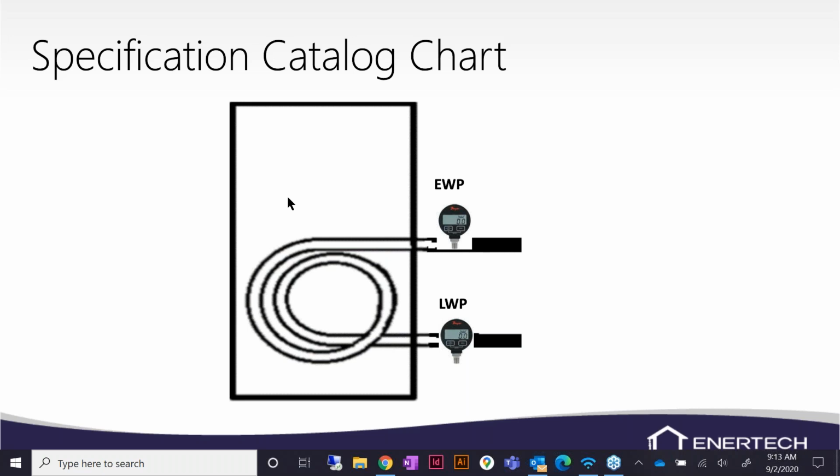We'll get to that kilowatt reading here in just a second there, Jason. When we get over to that I'll kind of explain that a little bit as well. And that kilowatts is basically just the compressor though. It's basically checking the power supplied in order to get the BTUs out of the unit. So we are just looking at the compressor on that. Okay. So again, pressure in, pressure out, and do the math on it.